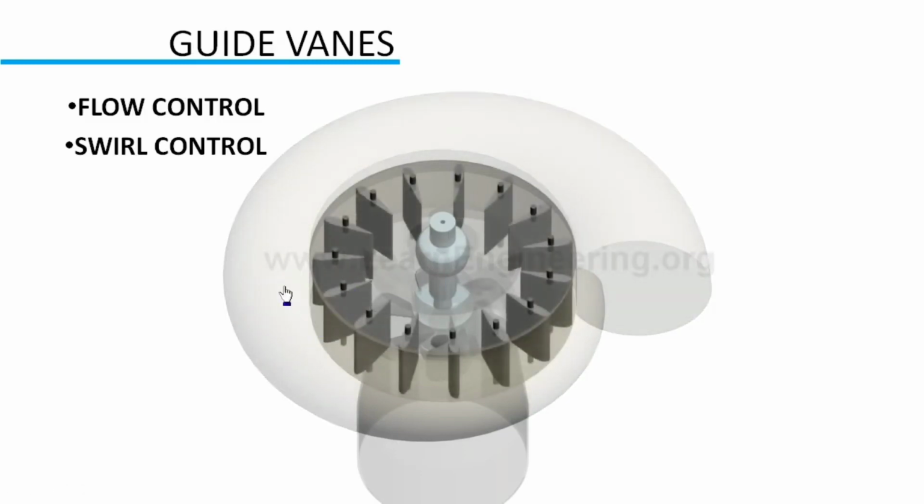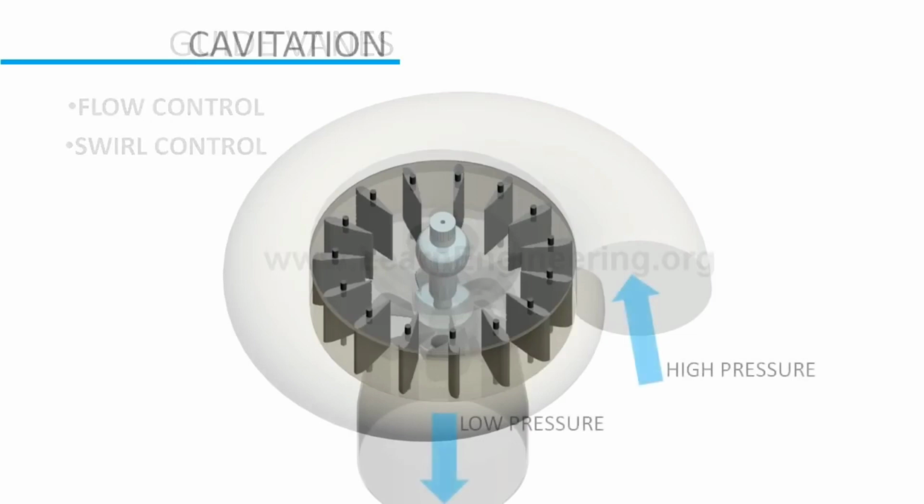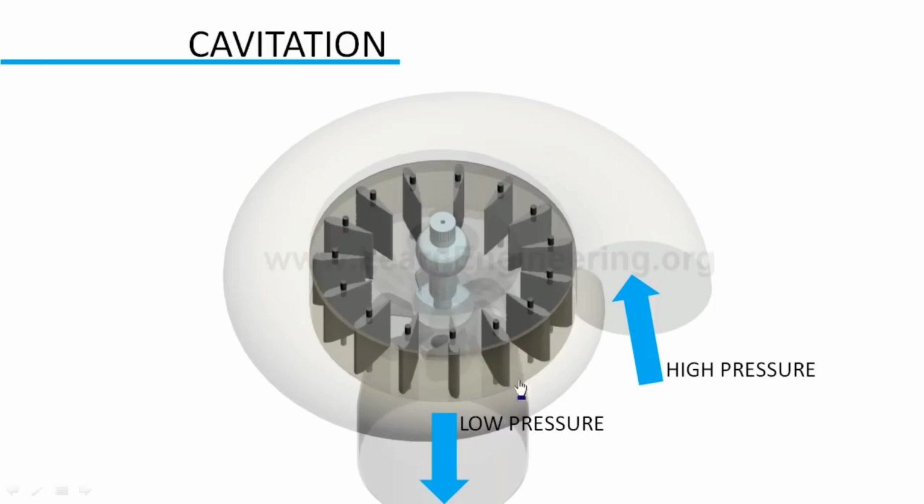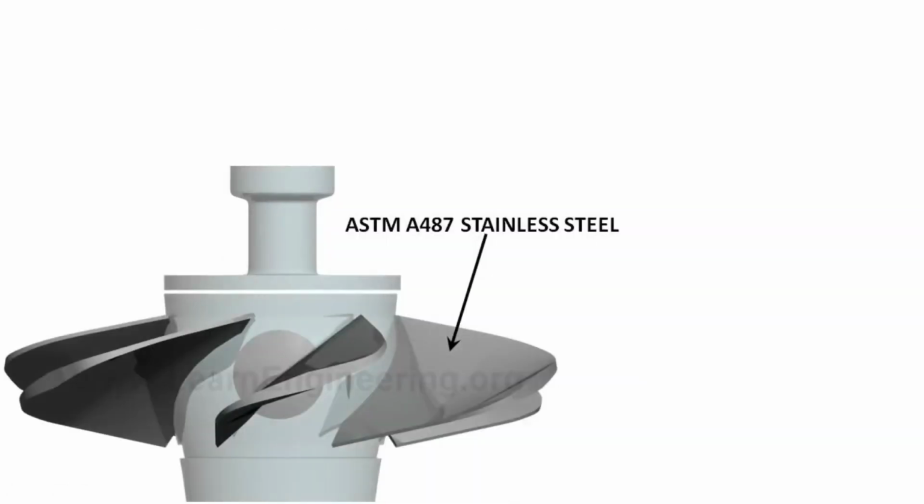The biggest challenge in the design of a Kaplan turbine is how to overcome the problem of cavitation, which causes material erosion and vibration. Cavitation is unavoidable in a Kaplan turbine since in most regions the pressure goes very low, but damage due to cavitation can be reduced by using a suitable draft tube which transfers dynamic pressure to static pressure.